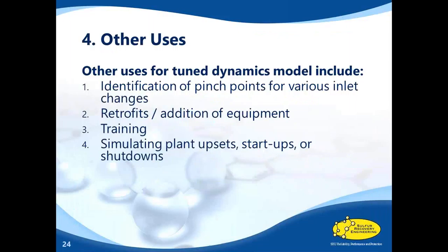Well, you just put the information into your tuned dynamic simulation. You're able to identify how the unit is going to be operating, and also identify what changes you need to make to the tuning parameters to set up the exact same control that you had with the first type of valve. It's very easy to do that. You can change your equipment information very easily with the model.